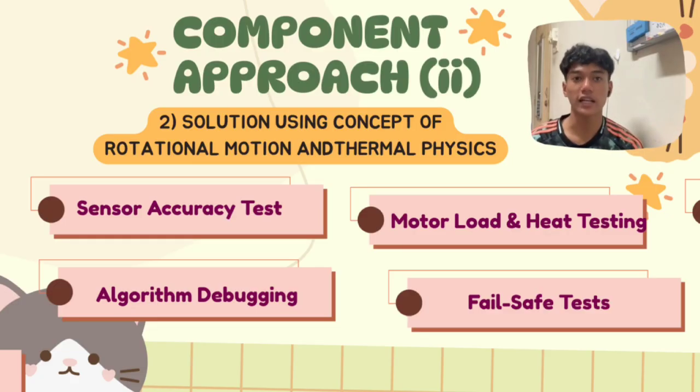Thirdly, we conduct algorithm debugging, where we simulate various heat levels and motor loads. This helps us to check whether the embedded software can adjust the motor speed in real time when the temperature rises, preventing overheating. Lastly, we carry out the fail-safe test, where we simulate overheating scenarios to confirm whether the blender can shut down or slow down automatically to protect the motor and the user.